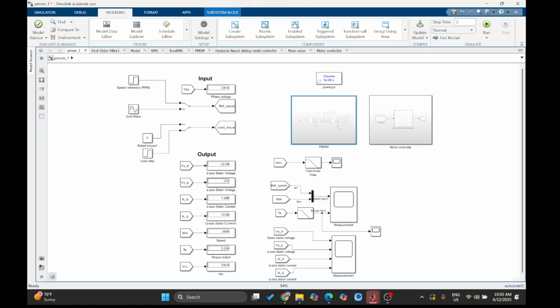We have a speed reference entering the SMC, then the SMC will compute IQ, then FOC will enforce the IQ and ID behaviors, then the SVPWM or PWM generator will control the inverter, then the motor will respond, and measurements feed back into the loop.